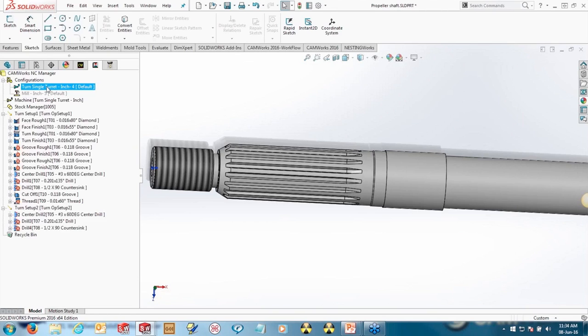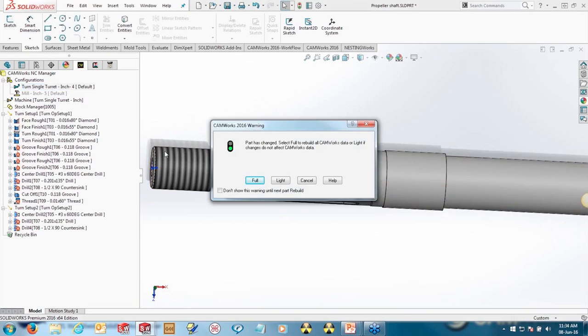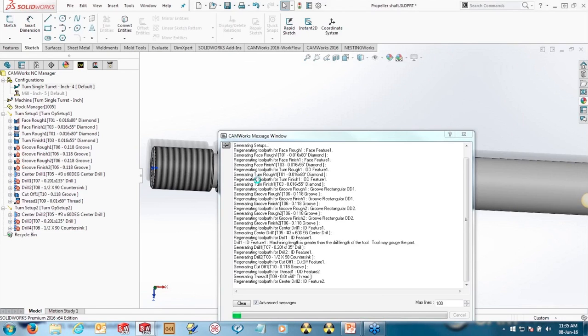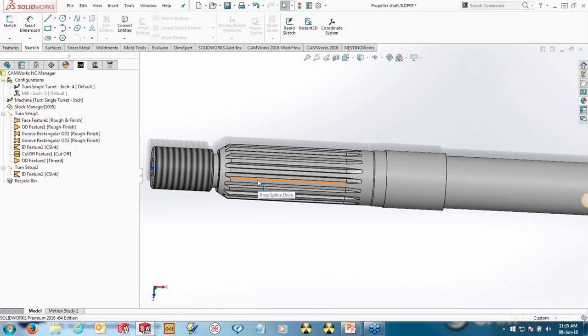We just basically go over to our CAM tab. Basically, we click on one of the tabs over here, and it's going to recognize that the model's changed. So we do an update on the lathe side. It's going to update the toolpath in here, and basically update the profiles for that. And then we'll switch it over to the mill side, basically updating the keyway cuts. It's going to change the toolpath to stick it further out. So we'll just let it do its update here. And this is a slick process. It's maybe 10, 30 seconds maybe to go through and update that particular toolpath.